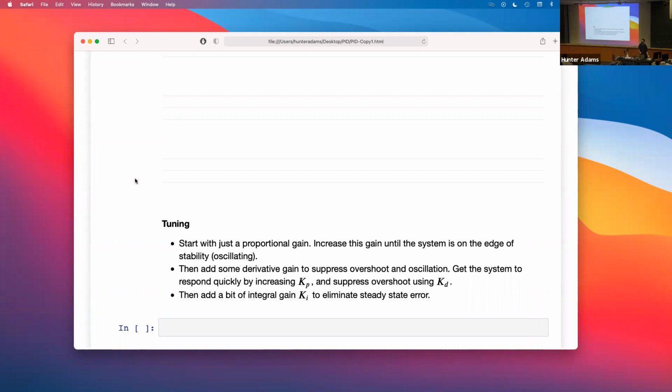However, this motor acts like a low pass filter, right? So if we were sending it different PWM commands at 10 kilohertz instead of 1 kilohertz, it's going to just smooth that out in the same way that it did the 1 kilohertz. So I'm not exactly sure how much benefit you would actually get from that. Something people might experiment with. Yeah.